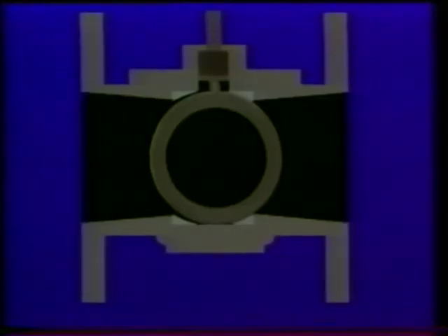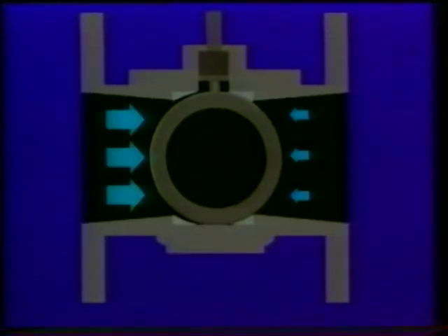Rotary valves are also affected by static forces, but in a much different manner. In ball valves, such as this, as well as other symmetrical valves, there is no unbalanced static force that the actuator must overcome. However, the frictional force created between the seat and valve trim is extremely high. With a full ball valve, this friction exists throughout the valve travel and must be considered when sizing an actuator.